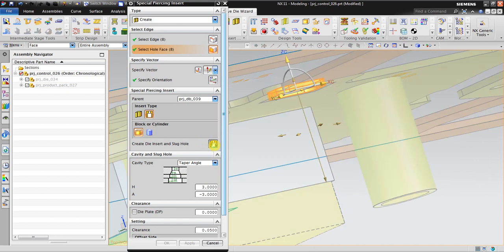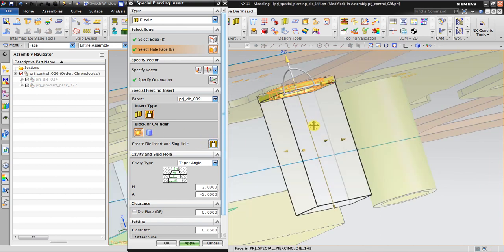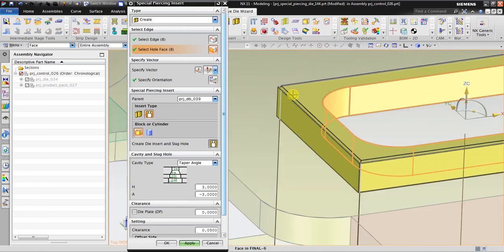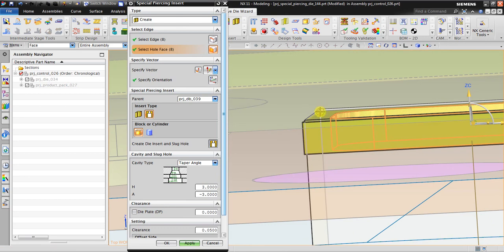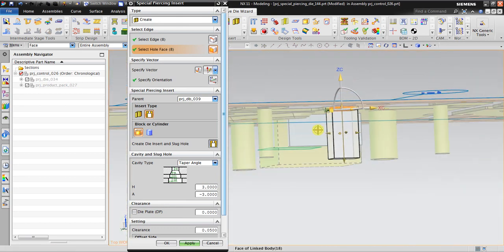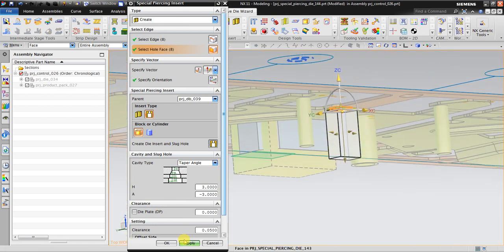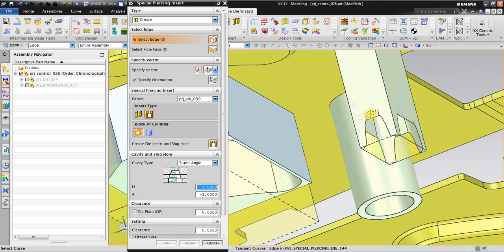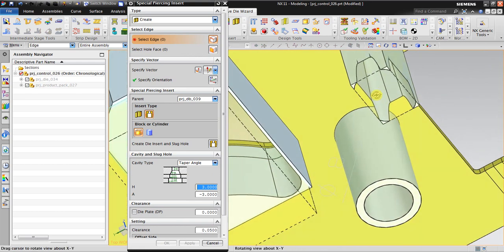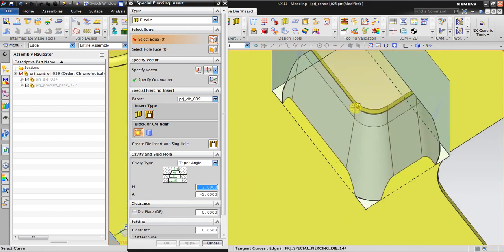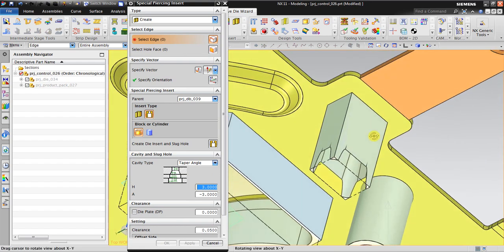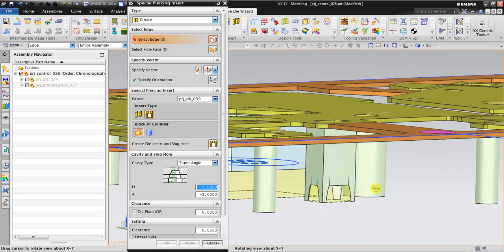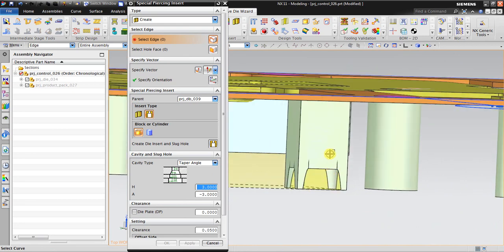Now you can see I slightly add to the top, so it's going to be the same thing like this one. You can see this is because the taper angle cuts in here. So you must go to Synchronous technology to trim the unnecessary shape like this one.